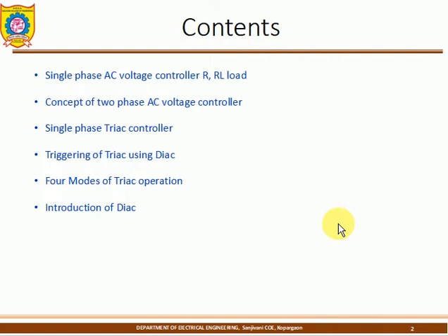It occupies some space and produces heat. When you touch near the fan regulator box, you realize the heat, and the plastic on top is melted due to the heat. Inside, a wire wound variable resistance is used, and by varying the point you achieve the resistance.